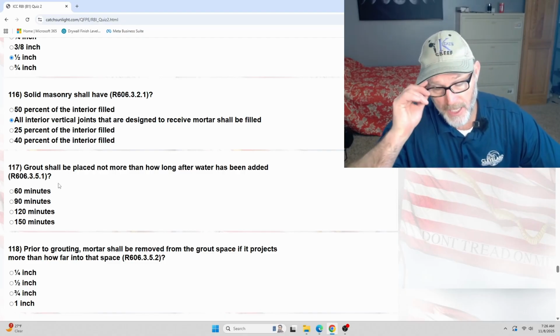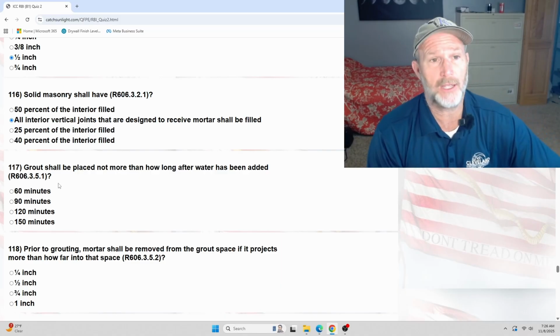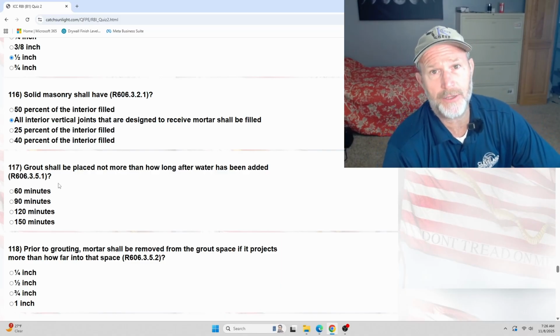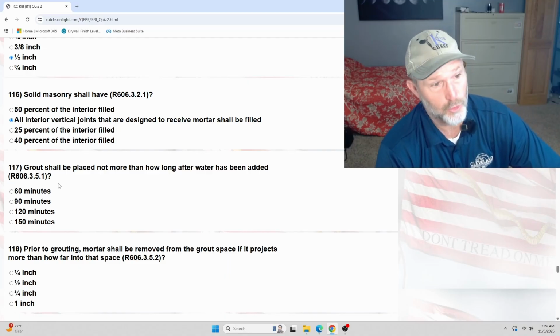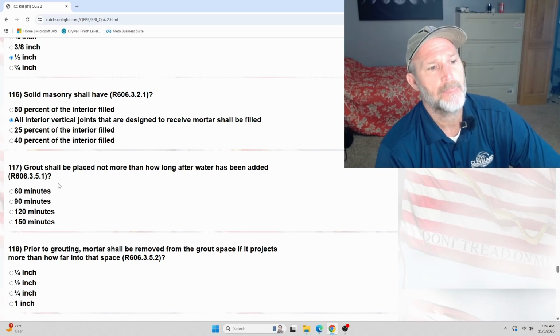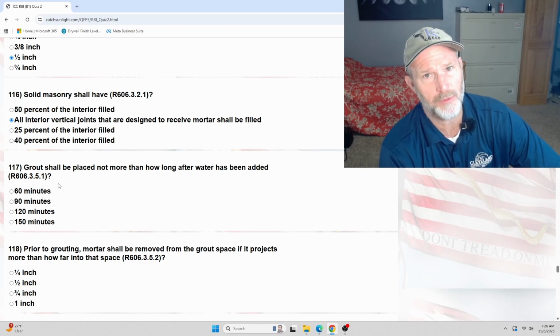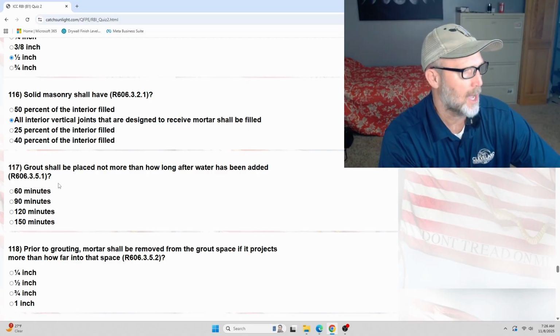I was just doing a job. This is kind of interesting. It's worth pointing out. We had a company come out to the job site pouring concrete. They did sidewalks and engineered sidewalks. I mean, a crazy high level of quality was necessary. The truck was batched out in the parking lot and then delayed for 2.5 hours before coming in. They poured, it was just too hot, and it started spalling within like 3 or 4 weeks. So it demonstrates that when you are mixing your concrete, there is a time that it's useful. You go past that time, it's not going to have the proper strength. So I'm just using that as an example.